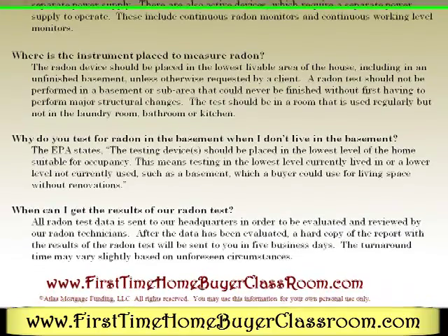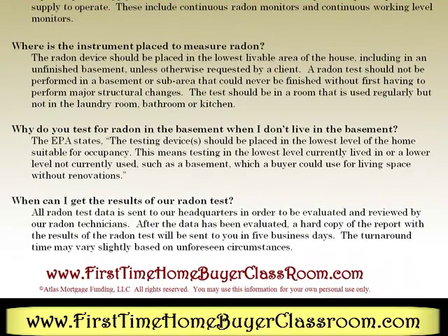Why do you test for radon in the basement when I don't live in the basement? The EPA states that testing devices should be placed in the lowest level of the home suitable for occupancy. This means testing in the lowest level currently lived in, or a lower level not currently used, such as a basement, which a buyer could use for living space without renovations.